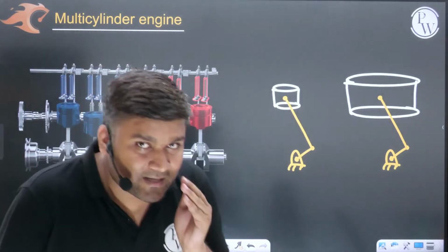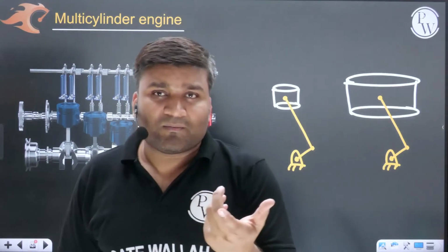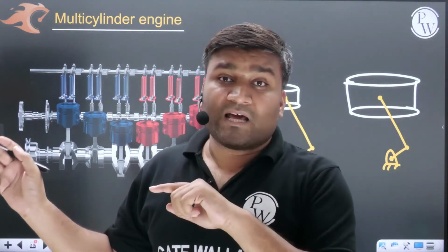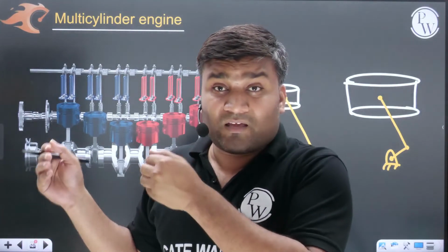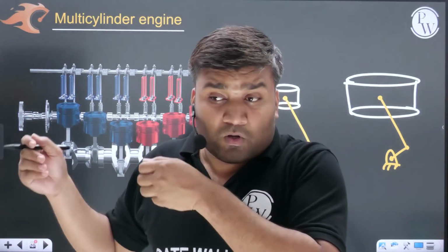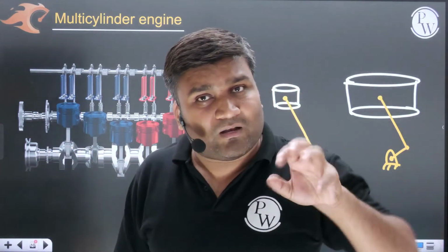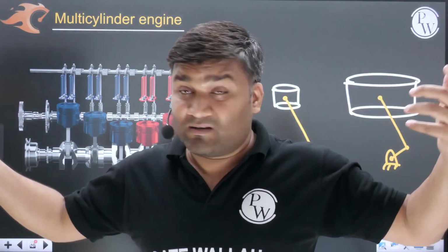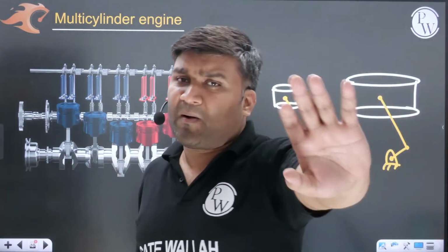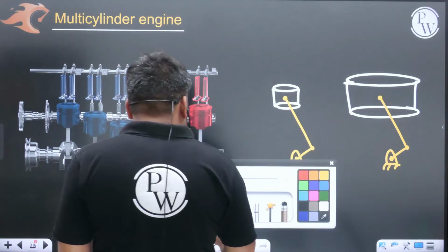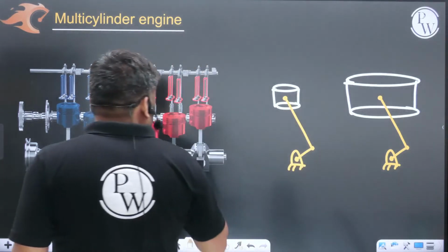Yes sir, it will increase. Obvious thing. Multiple small-size cylinders are giving power to the same crankshaft. Obviously, power as compared to one is multifold now. It has increased. But that was never my aim. My aim was to make the torque theta diagram uniform. Maintaining uniformity was my aim.